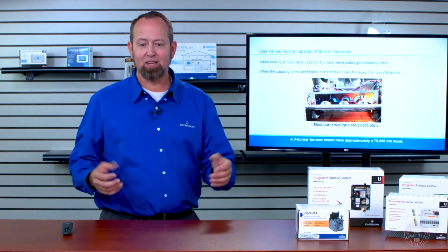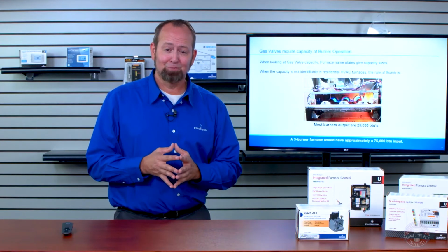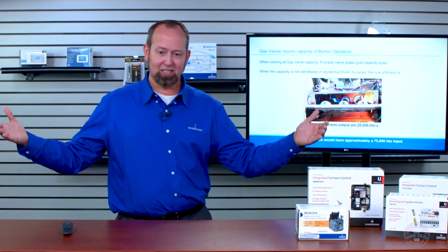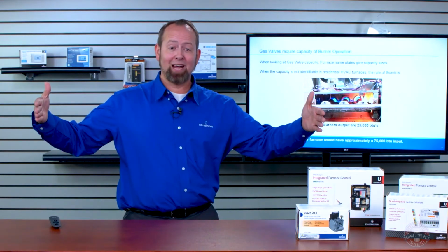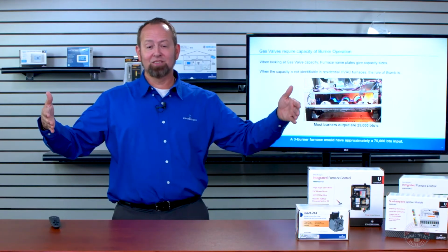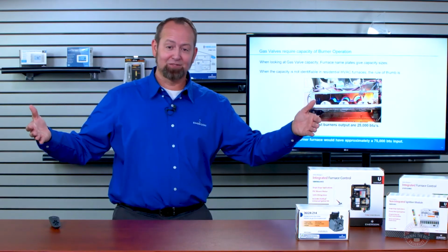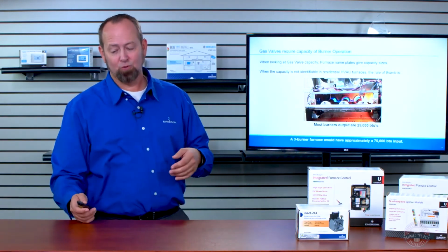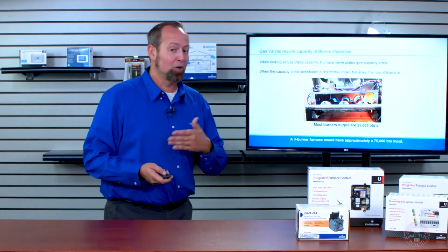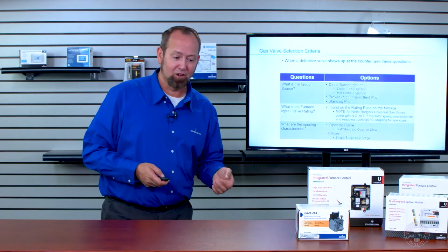Now there's instances a 3-burner may be called a 65 or an 85,000 BTU, but it's going to be fairly close. And by and large, most of your residential furnaces, you can get into the 5 and 6 burners, getting you to 125, 150,000 BTUs. The 150,000, the 24-inch wider cabinets, the old furnaces are the ones. They're going to have plenty of room for a larger gas valve anyway, so it's typically not an issue. But those are going to be the ones that you would be concerned with capacity-wise for most of our universal gas valves that we have to offer.